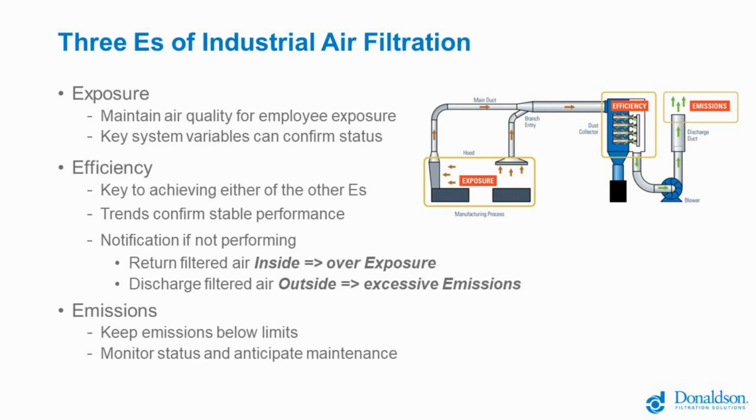Also, you want to make sure you recognise the impact of design changes to a system that's already in place. For example, it might be a good idea to add a secondary or a HEPA filter to minimise the risk of excessive emission. However, adding this level of additional restriction will impact the overall volume in the system and could reduce the capture velocity and thereby increase the exposure levels of the employee.